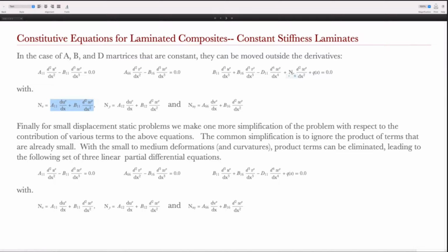In that case, what we do is we take the Nx and turn it into a constant term. We assume that right before buckling, there is an Nx value which is constant and is in front of this term. It is computed by this, but it remains constant; it no longer changes with W. That is, we find the Nx mostly from the in-plane loads, ignoring the W's, and then use it as a constant load here.